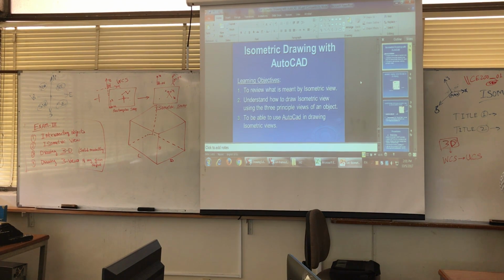Third, only thing, when you are drawing a circle, keep it in mind, you don't go and directly select circle. You select ellipse and then tell the computer that it is an isocircle. How? We will now practice it.